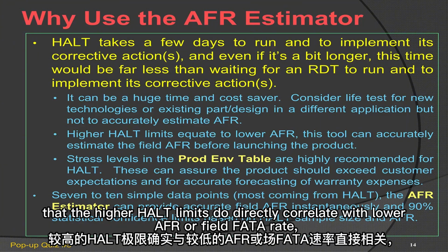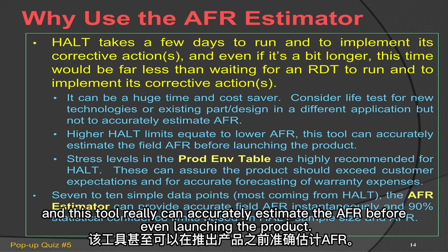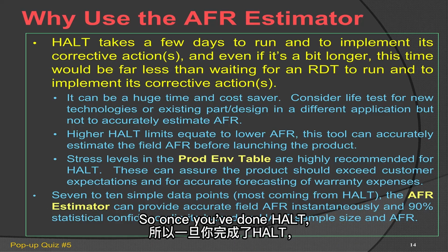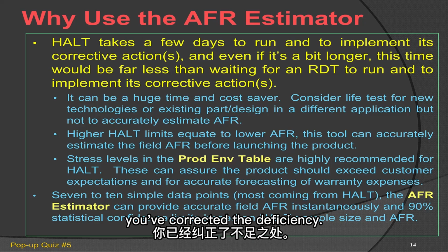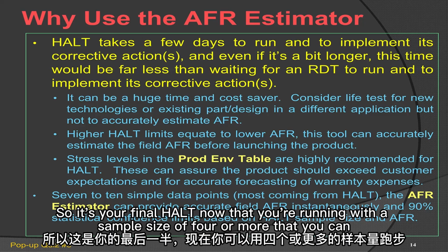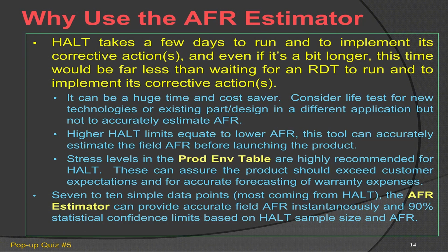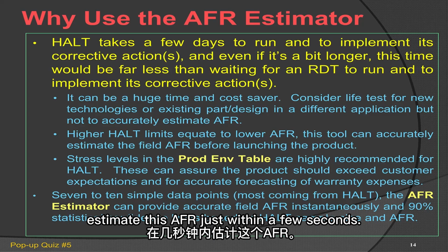Realizing here, of course, that higher HALT limits do directly correlate with lower AFR or field failure rate, and this tool really can accurately estimate the AFR before even launching the product. So once you've done HALT and corrected the deficiencies, it's your final HALT that you're running with a sample size of 4 or more, and you can estimate this AFR within just a few seconds.